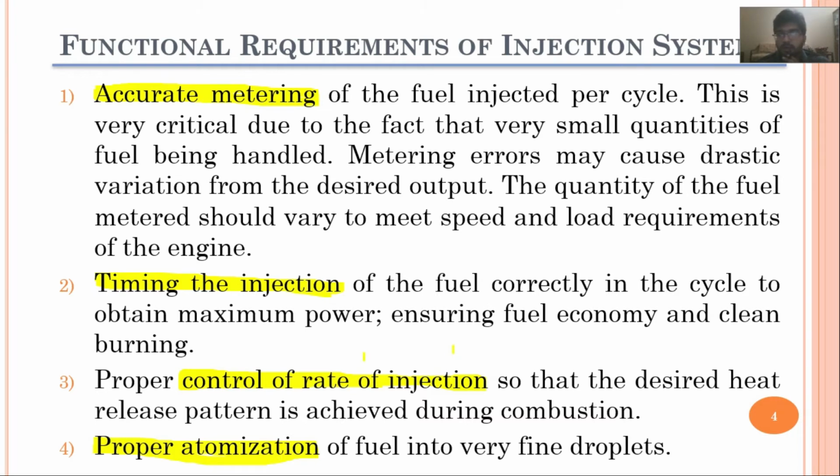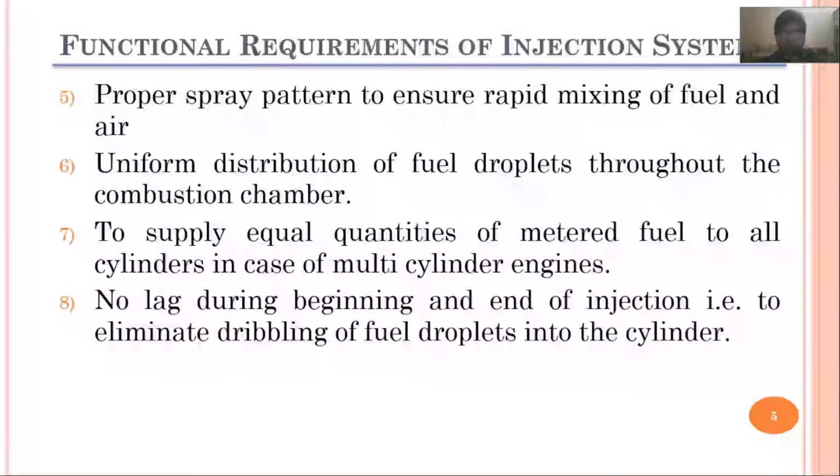So what are the important functions? Number 1, accurate metering. Number 2, timely injection of fuel. Number 3, controlling the rate of injection. Number 4, proper atomization of fuel. Okay, now moving forward. Now another important function is proper spray pattern.